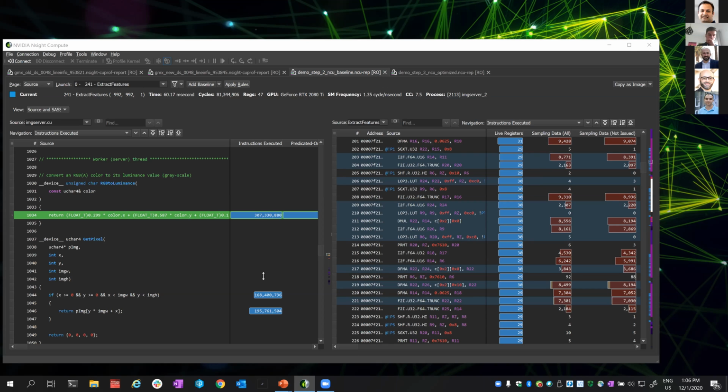And Nsight Compute can also collect this NVTX information. You just have to use the --nvtx flag, and then it allows you to, for example, filter to see, okay, I only want to see kernels that are in a specific NVTX context. I only want to see kernels that have the preparation phase range on the call stack already during collection of the data, for example. Or I want to turn on profiling at a later point.